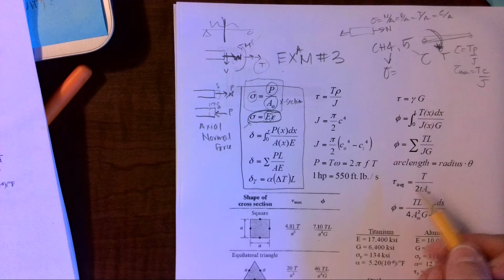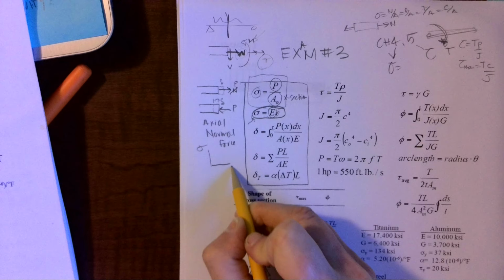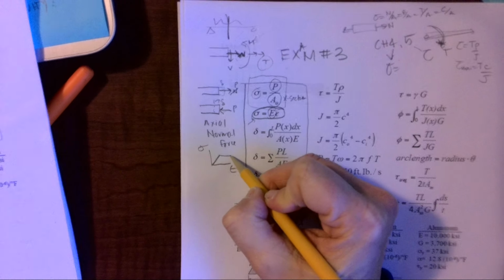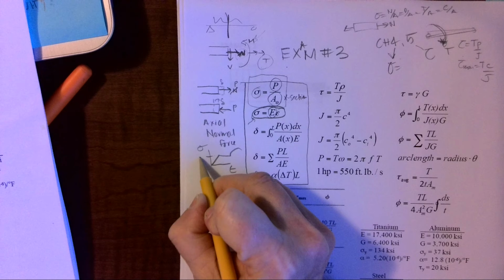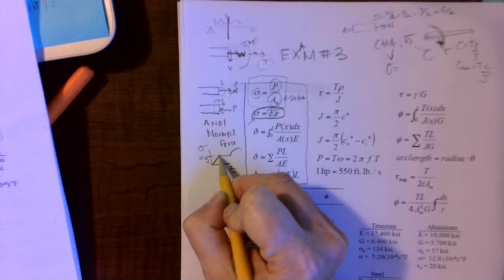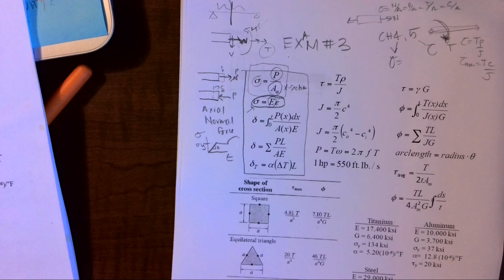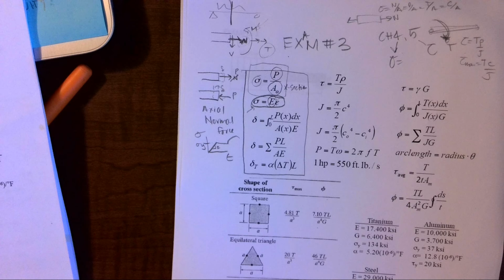And if you all remember, I can have a stress strain diagram, and we usually have an elastic region, a very long yielding, kind of come back up, have an ultimate, and this is our yield stress. It's where we have this linear behavior between stress and strain. As I pull on my rubber band within that elastic region, I will have a lengthening, and when I let go of that rubber band, it will go back to its original shape, and I don't have any permanent deformation.